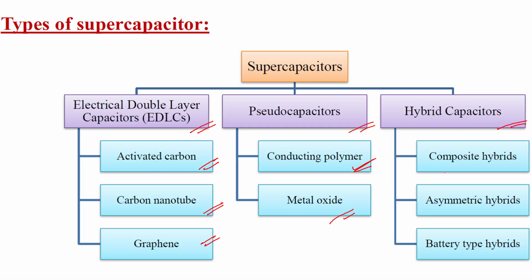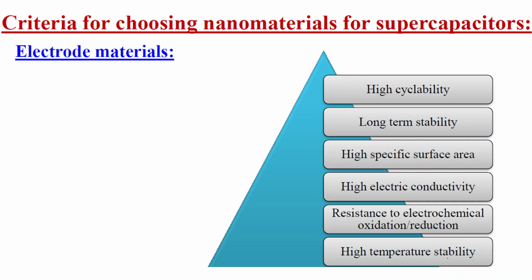In the case of piezoelectric nanogenerators, zinc oxide, cadmium sulfide, gallium nitride, PZT piezoelectric materials, and PVDF, or polyvinylidene difluoride, are the mostly used materials. Now coming on to triboelectric nanogenerators, which are based on frictions, contact electrification and electrostatic induction. They can be coupled with piezoelectric, pyroelectric and thermoelectric nanogenerators to get more output.